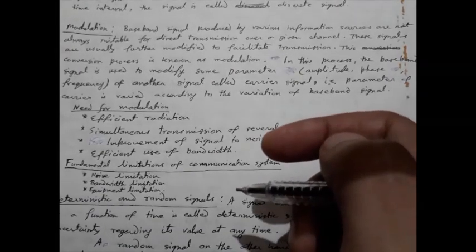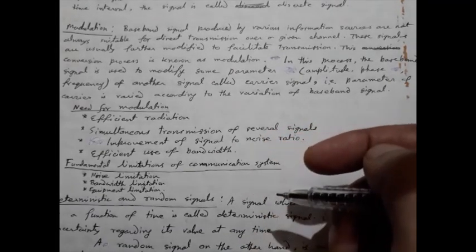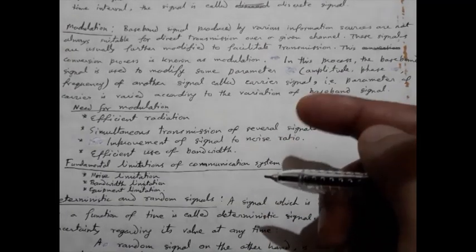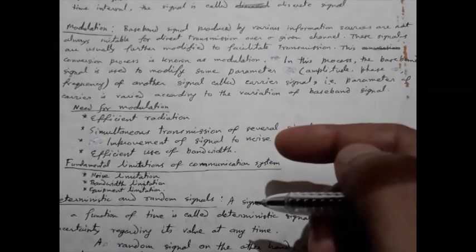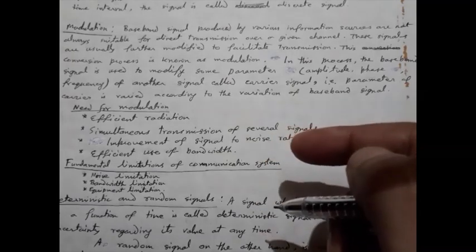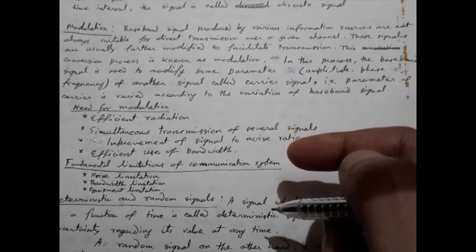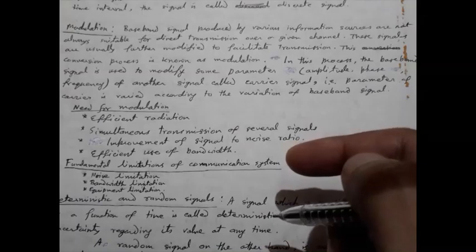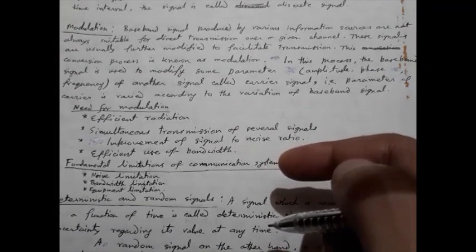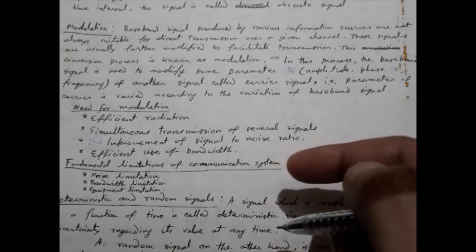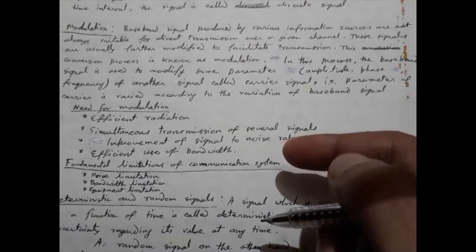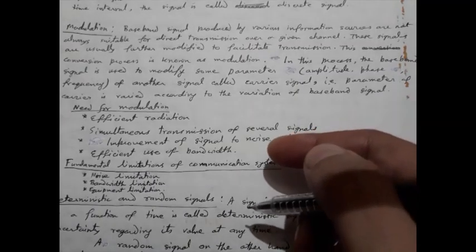Now if we consider the voice frequency is up to say a few tens of kilohertz, 20 kilohertz is the maximum limit, then the corresponding wavelength would be of the order of a few hundred kilometers. That means if I want to transmit the voice signal, we require an antenna of length half of hundreds of kilometers, that means of the order of 50 kilometers or more. Now an antenna size of 50 kilometers is an absurd idea.